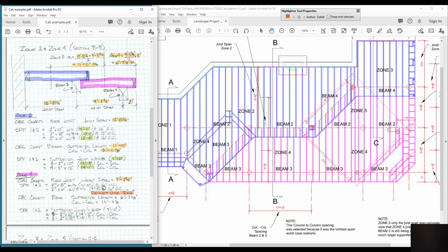This, we only have two different options. That makes sense because anything else becomes too strong, too big. Our span is only 9 feet. So here I have a couple that I've selected, for 9 foot 3 3/4. Look at that. The 2x6 could handle a 9 foot 4. I'm not going to go with that. So I'm only going to be using the 2x8s with strapping, which is the base value, and therefore we can get away with something that is only, let me put that in the green, that has the capability of spanning 11 feet, even though we only need 9. So that's a very simple one to look at.